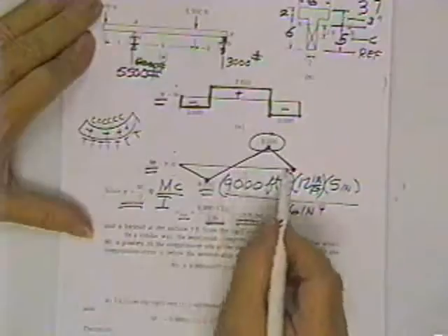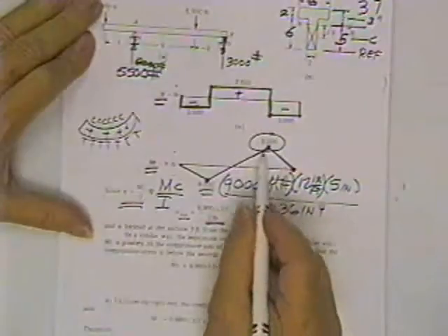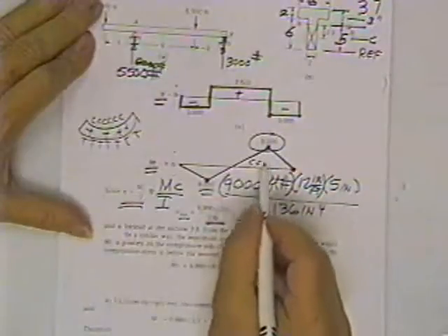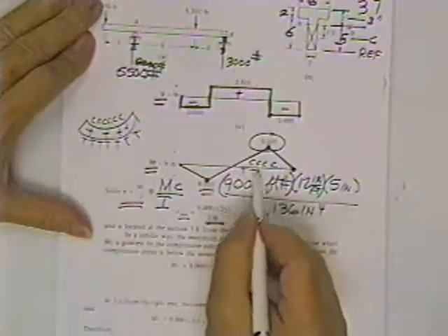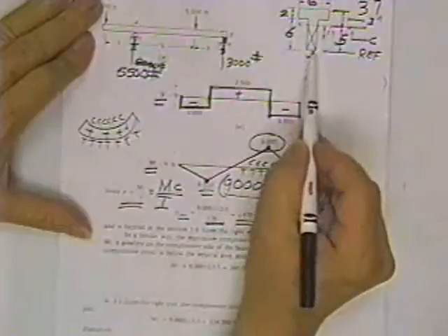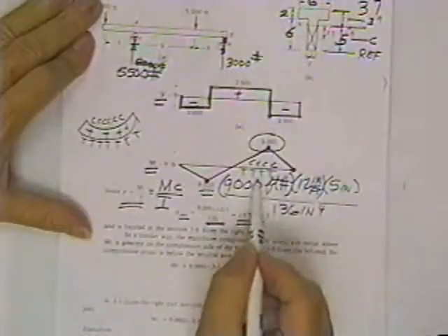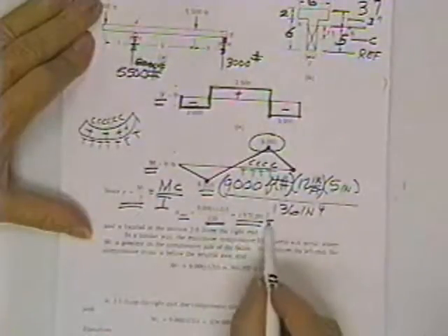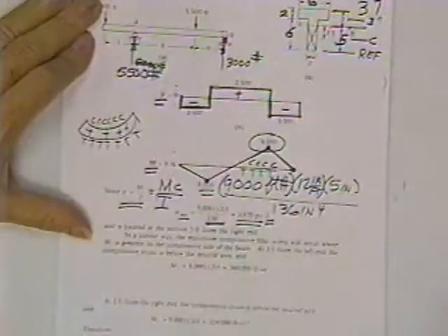And therefore, in regions of positive bending moment, the moment is above the line, you have compression on the top fibers, you have tension on the bottom fibers. So when he went to the bottom fiber, he was finding a tension stress. That's why he puts tension for that stress. It'll be very important you're able to do that. I think it'll be very likely they'll ask you whether it's a tension stress or a compressive stress.